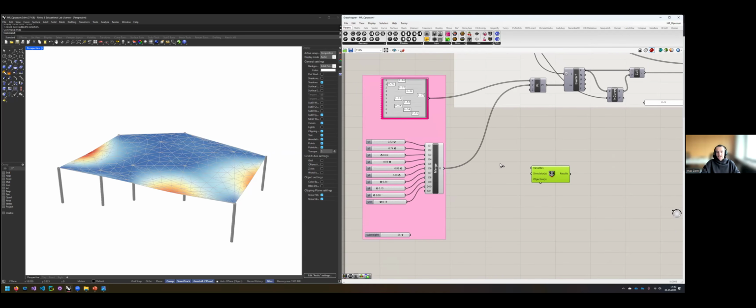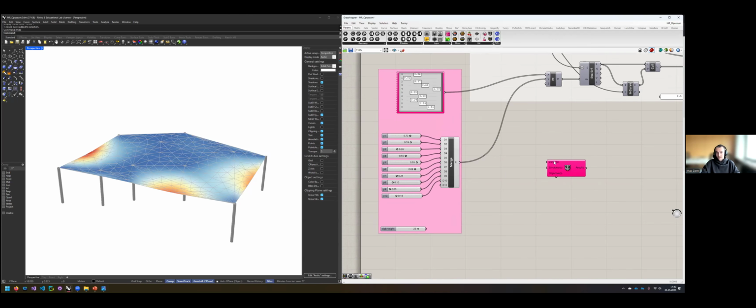And because it's very tedious to manually connect all these different sliders, there are two ways of doing this a little bit more automated. If you right-click on variables, there's the option to link all variables, which would now be all sliders and all gene pools on your canvas.